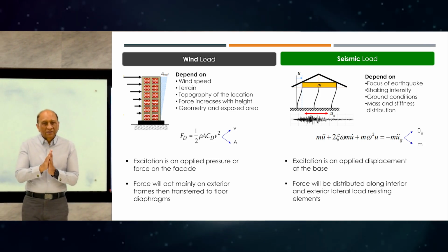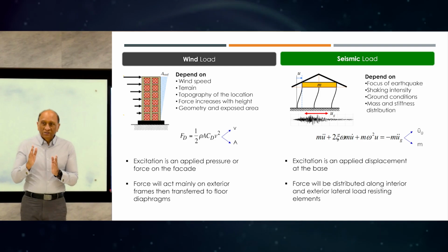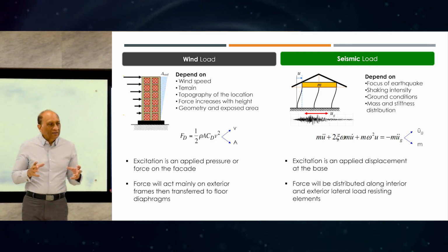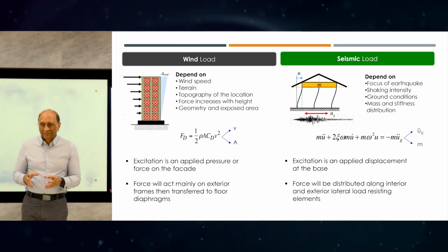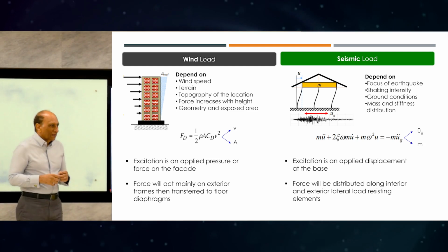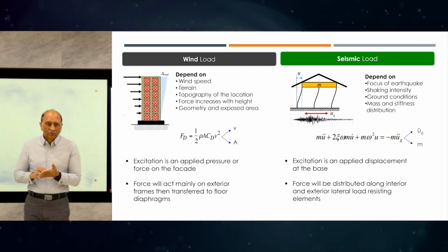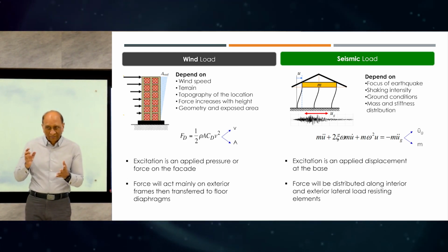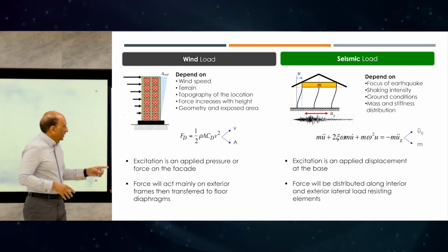So not only velocity, but we also need to worry about the building acceleration, because acceleration can make people dizzy. So one of the key controls on the building is acceleration due to wind that we have to check. And once again, codes will not give you any formula to calculate the acceleration due to wind, except the Canadian code, some portion or some other. Normally they don't have it because they're not dealing with tall buildings.